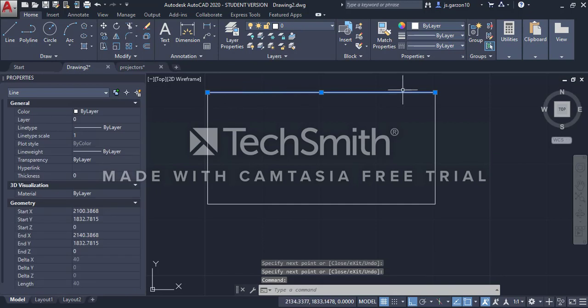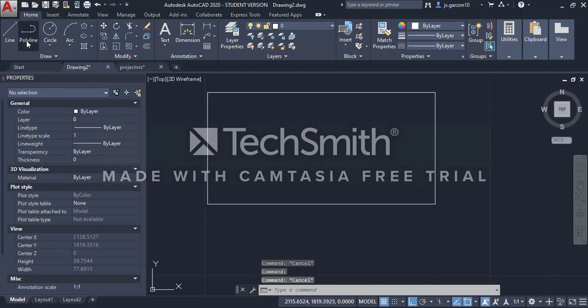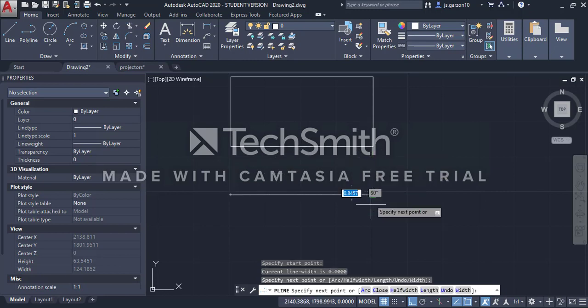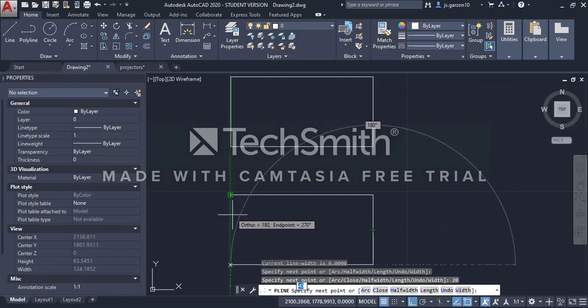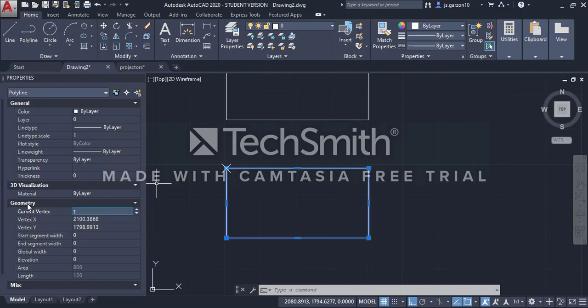As you can see here, each line is split, so each one is not connected, it's just a simple line. If you draw the same object using a polyline, you can see that all of them are connected, and you can switch between each vertex using this property option that is called current vertex.